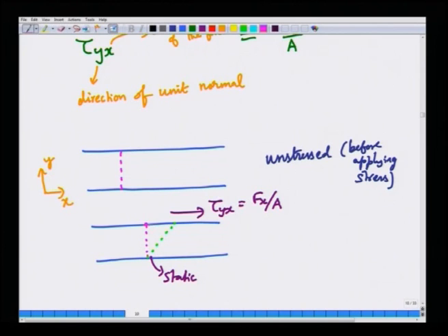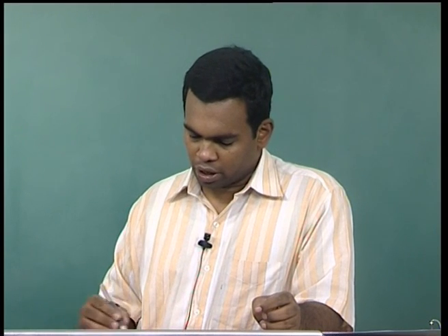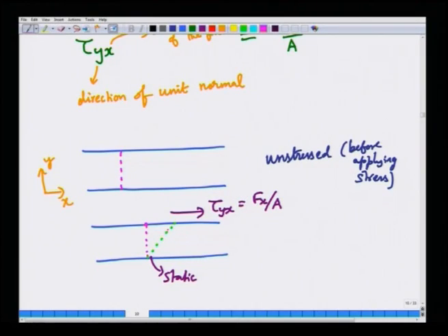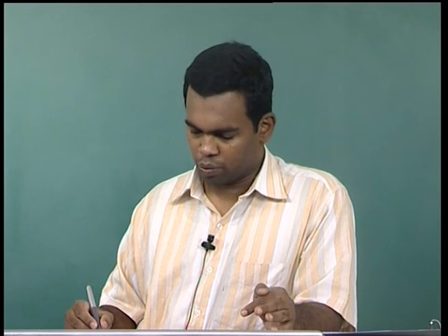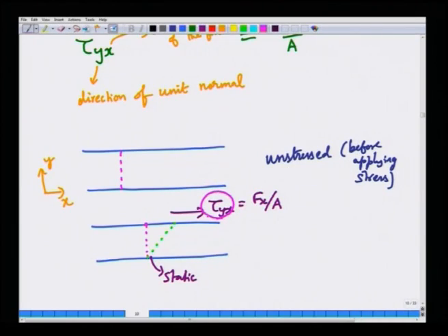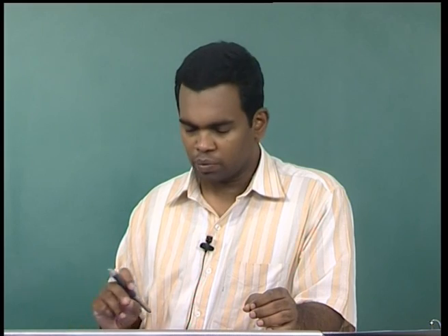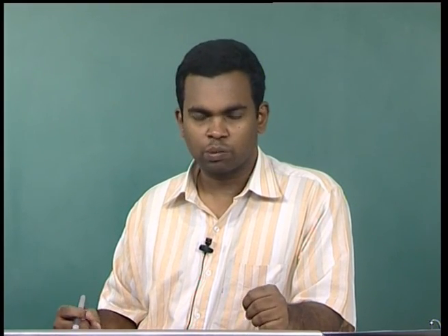So, in general, an elastic material deforms upon application of shear stresses, but the points do not continue to keep deforming. After achieving a certain deformation, the material stops deforming. So, if you apply a given stress tau y x, you do not find that the material keeps on deforming; the points move somewhat, and then internal stresses develop within the elastic material that resists further deformation.